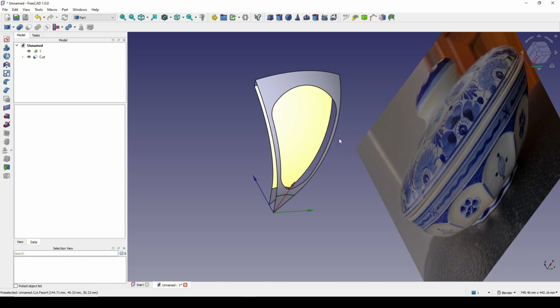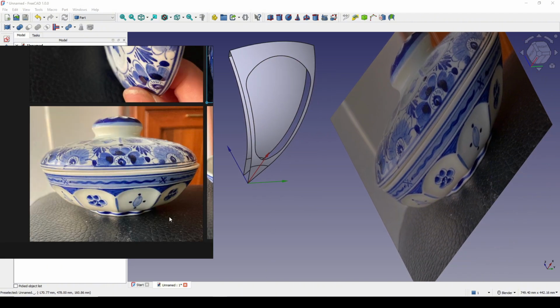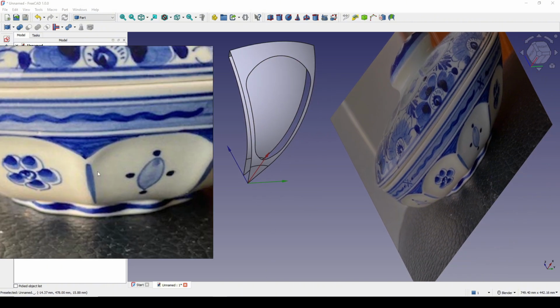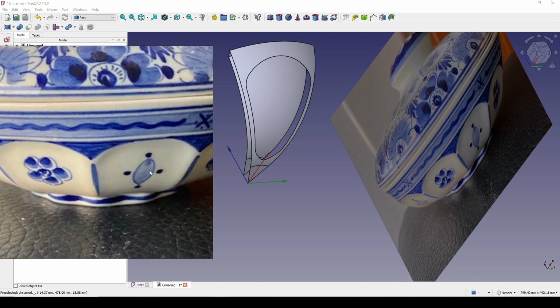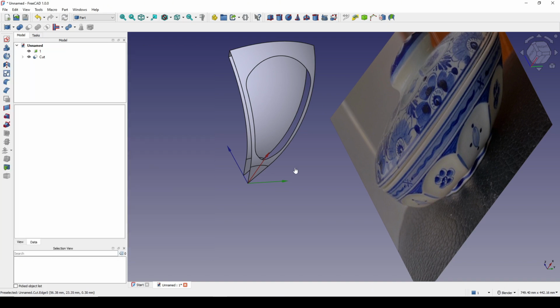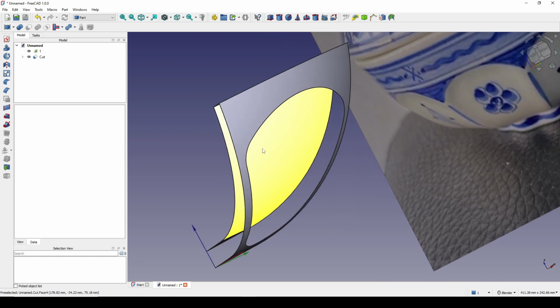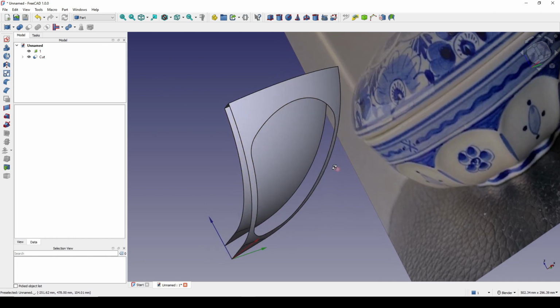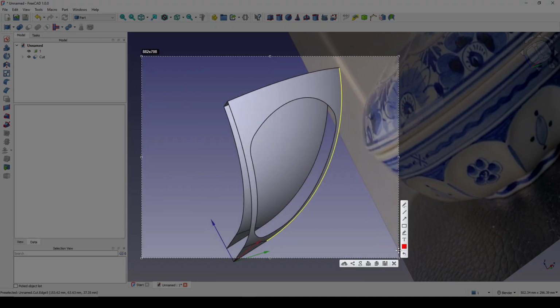You can see the surface in here go inside, so I need a curve inside to put the surface inside. So I need to create a freehand B-spline from this point to this point and curve inside a little bit to push the surface inside.